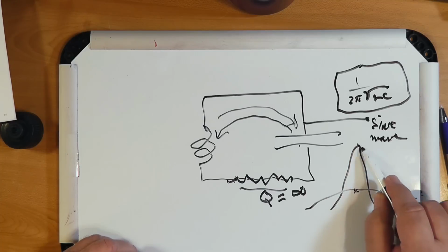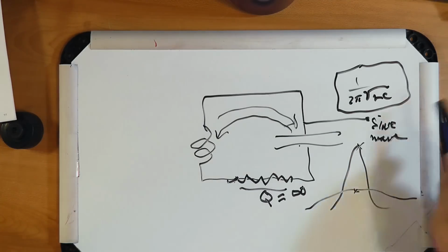This is the multiplication factor of the Q. Because you take the voltage applied and multiply by the Q to get the total voltage here, and that can lead to some horrendous circulating currents here. And unless you make your oscillator parts out of very strong stuff, you're going to get a lot of I²R losses. I know this sounds a little weird, and some of it is even a bit beyond the extra, but nature works the way nature works. Okay, so there we go.